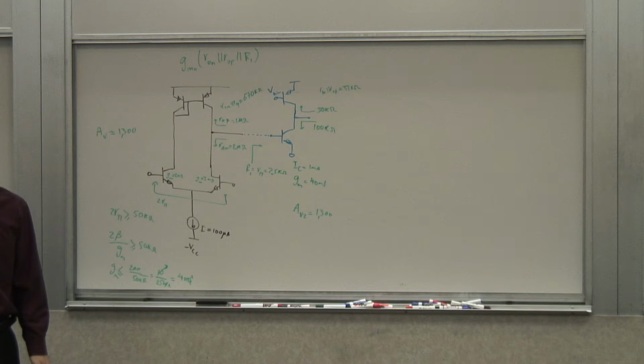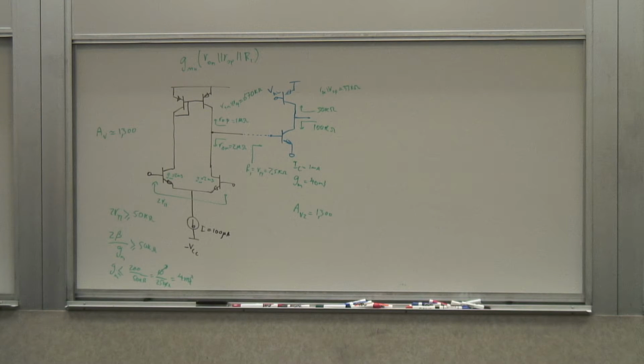So it's obvious we need something in between. Right? And you can guess what we need. I mean, that's obvious at this point, right? You need a buffer. You need a buffer that has a higher input impedance and lowers the output impedance so you can drive something.